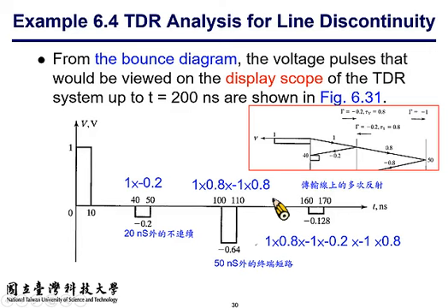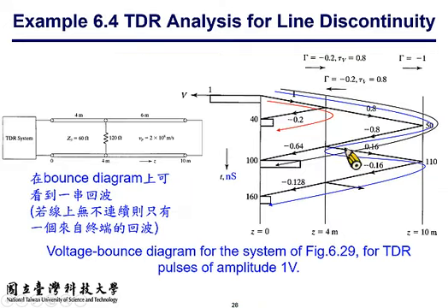So if you continue the bouncing diagram, you shall observe that there is a third impulse returning to the left, which is caused by what? Which is caused by this path, the blue line, okay? Transmitted, reflected again, and then transmitted. And of course, you will have the fourth term, fifth term, sixth term, and each following term will add up to reflection.